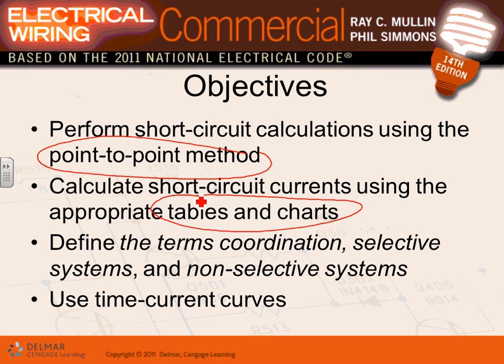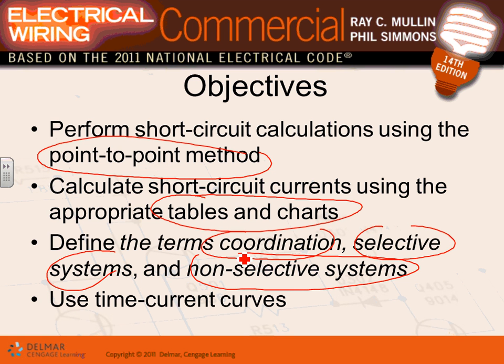Coordination. The term coordination, selective system and non-selective system. These are very simple topics, guys. Brian, if I ask you to go change that ballast energized, which you're not supposed to do, and accidentally the 120 hot touches the frame of that fixture, which circuit breaker should trip? That one here or the main of Dunwoody? If that one trips, you have coordination. If Dunwoody's main trips, you don't have coordination. So everybody understands why this is coordination.